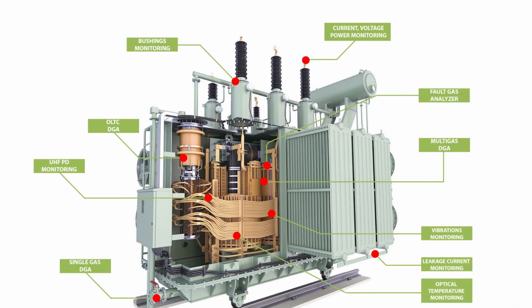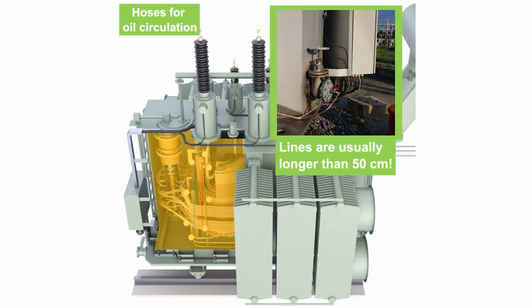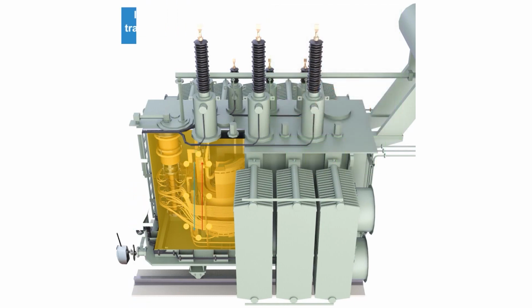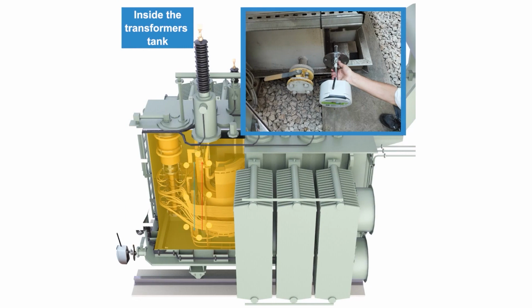Our monitoring solution for power transformer includes DGA monitoring, bushings monitoring, tangent delta, capacitance, phase angle and imbalances, PD monitoring, voltages, currents and power factors monitoring, optical windings temperature assessment, moisture, fault gases monitoring in OLTC chamber, UHF PD monitoring, vibrations monitoring with modeling, core, and insulation leakage currents.